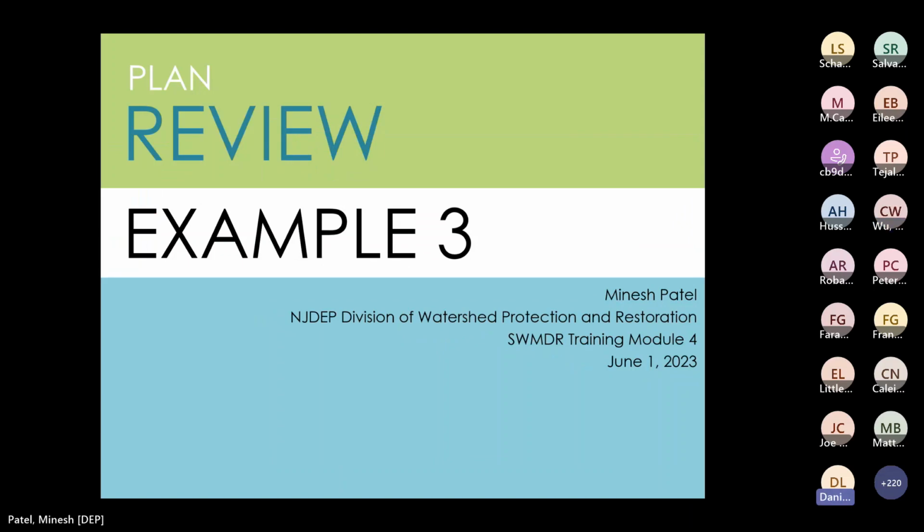Most of the designs I've seen are subsurface infiltration basins with some green roof component to lower the CN, but that's really the extent of it. I haven't seen too many distributed green infrastructure elements on these small properties.